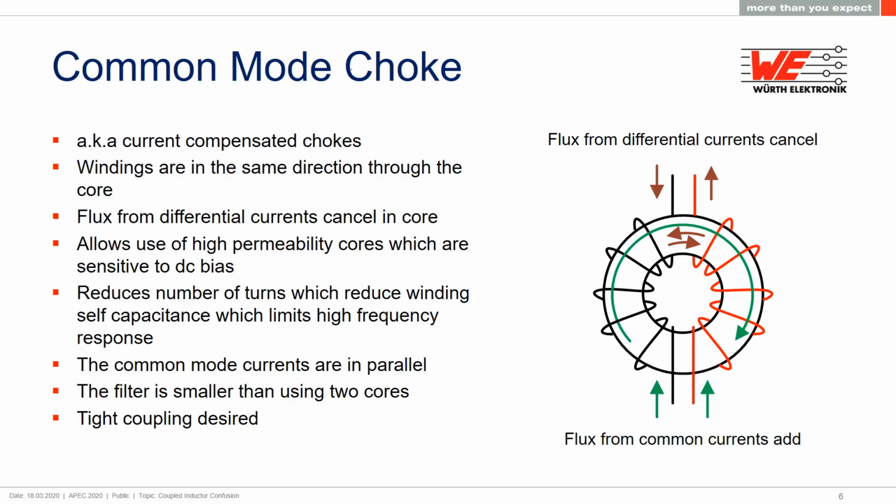The trick to operate at high frequencies, aside from using a high frequency material, is to keep the winding self-capacitance as low as possible, and to do that you want to have the fewest number of turns nicely spaced. You want tight coupling so that the differential currents completely cancel and you get the most advantage from the common mode currents going in the same direction.